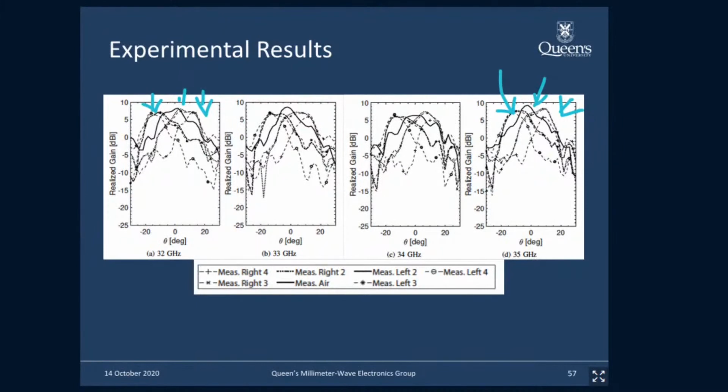Usually when you want to do beam steering with antennas, traditionally you have two choices. Choice number one is you have one antenna element and you mechanically rotate it. This is what they do at the airport with those aircraft radars, where the antennas are moving around, and you see this in ships and all that. Another way is electronic beam steering, in which case you need an array of antennas and you change the phase shift, and you know how that works. So you can do the beam steering that way.